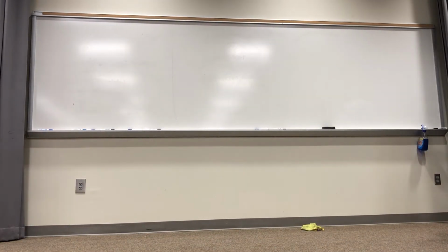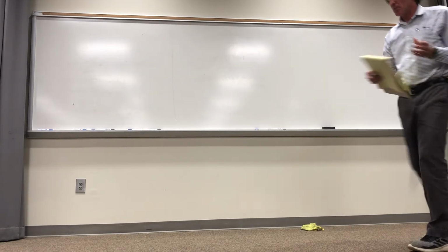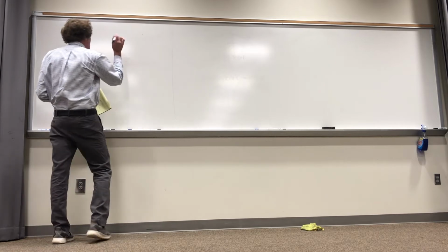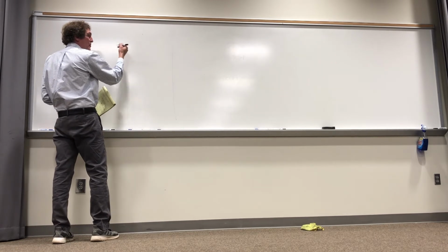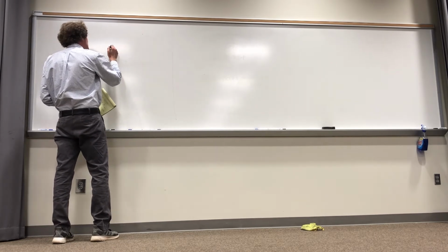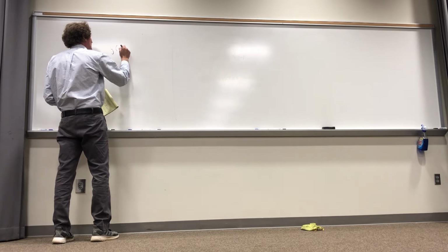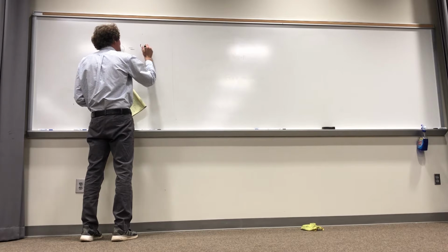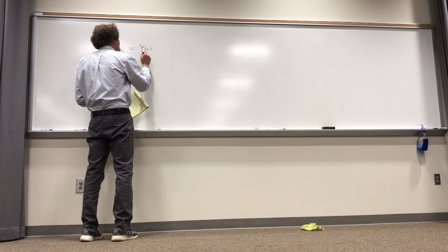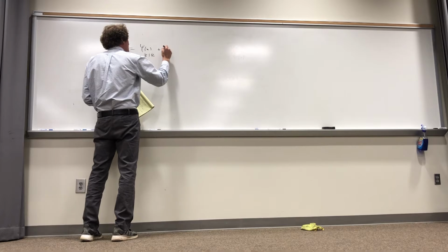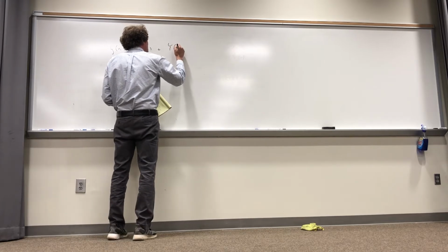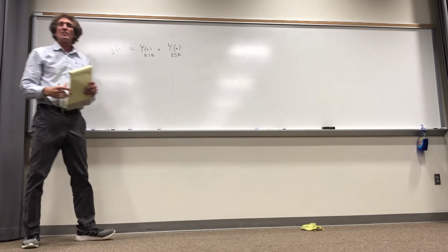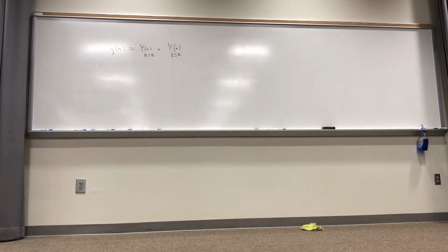Well, with Z transforms or difference equations, no matter how they fit, you can talk about something where you're going to get two responses that will add together to make up the total system response. We can say that y of n is really going to be y of n, called the zero input response, plus y of n for the zero state response. Now, I'm not going to spend a lot of time on it, but let me explain this as best I can.